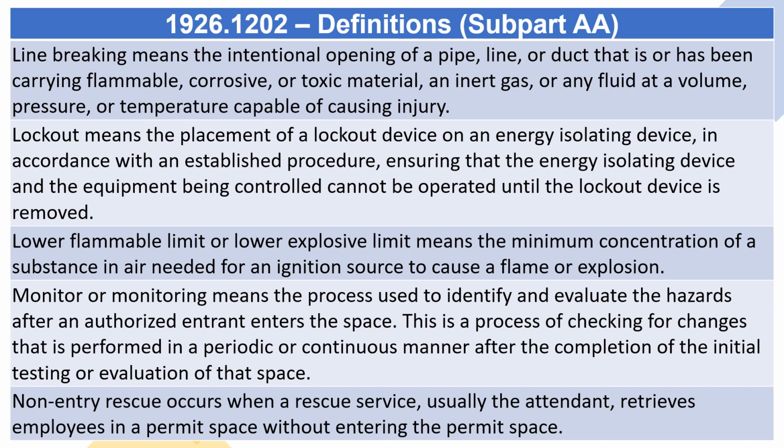Lower flammable limit or lower explosive limit means the minimum concentration of a substance in air needed for an ignition source to cause a flame or explosion. Monitor or monitoring means the process used to identify and evaluate the hazards after an authorized entrant enters the space. This is a process of checking for changes that is performed in a periodic or continuous manner after the completion of the initial testing or evaluation of that space.